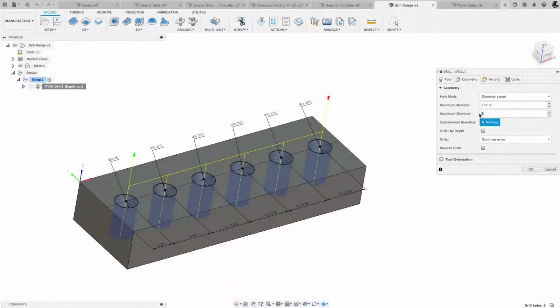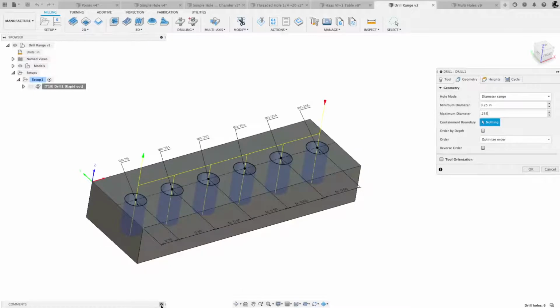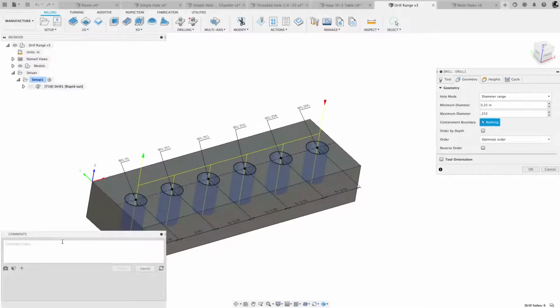And let's say we've got a document, or we've got a mechanical drawing. And let me see, can I put something in here? And on the tolerances, it'll be something like this: X.XXX, 3-place decimal, the tolerance equals .005.